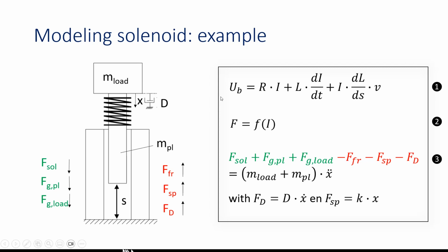In that case, a couple of things change, because when that solenoid heats up, the R will change, so the maximum current will change, it will be lower, so also the force generated by the solenoid will be lower. But also due to the changing R, the point in time at which the plunger reaches its maximum inner position will be at a different point in time.